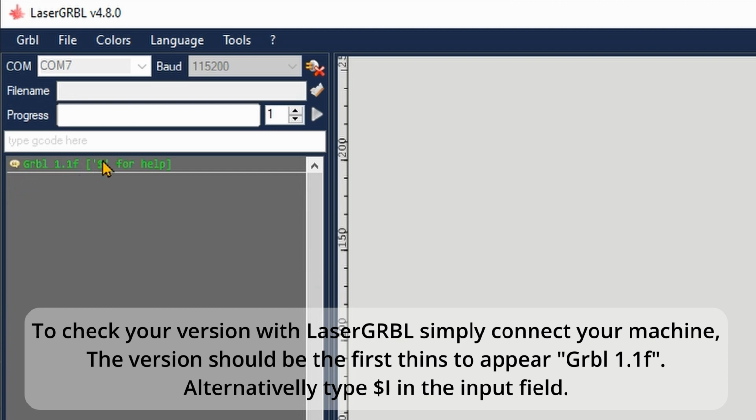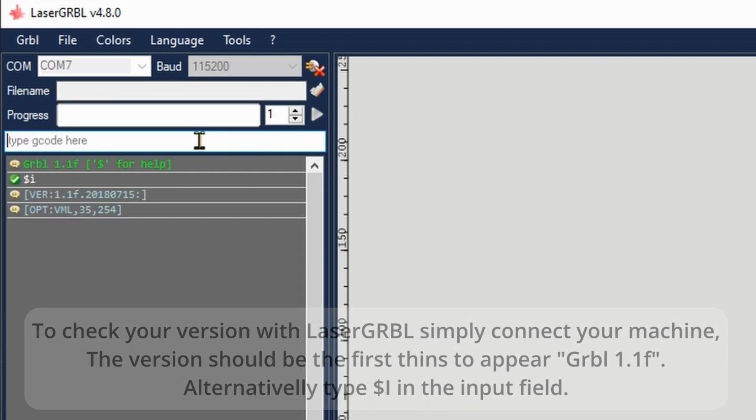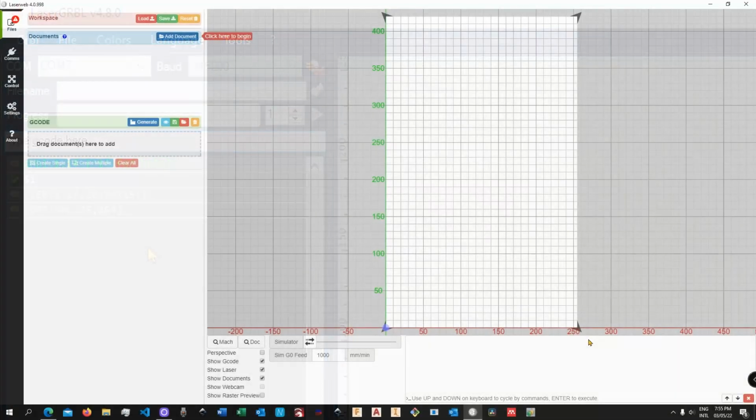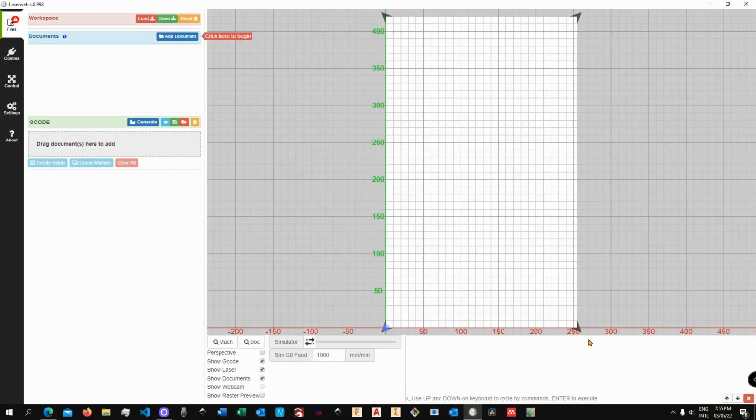However, that at times might not be a very simple thing, and that's because some manufacturers, some brands, are actually running a customized version of the GRBL firmware. So it is something that I would highly recommend you check with the brand, on their official site, or contact them to see if they have the update, and also if you can manually update the board like you would with a typical Arduino board.